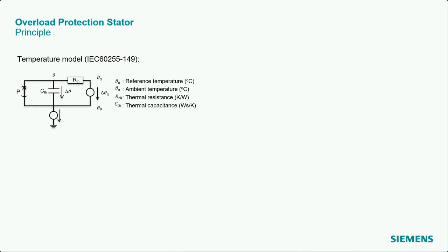And if you know that, you can also calculate immediately with the quantities that are related to the temperature. So instead of a current source here, we have a power source. This is the thermal capacitance. So we don't have a voltage across this capacitor, but a temperature difference. And here the resistor.